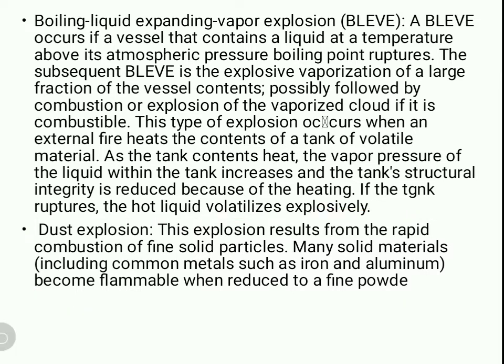Now the next type of explosion is the boiling liquid expanding vapor explosion, also called a BLEVE. It occurs if a vessel that contains liquid at a temperature above its atmospheric boiling point ruptures. Suppose this is a storage vessel. It contains a liquid and some space is given for the vapors.